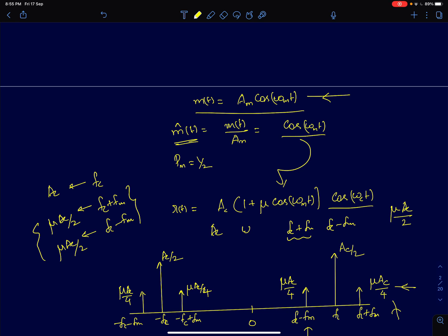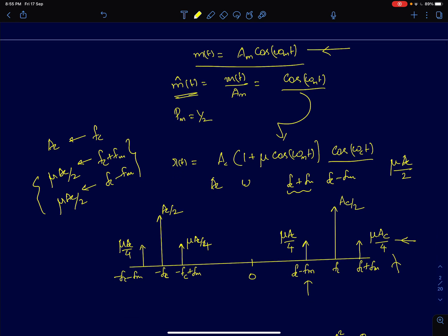Now, to plot its Fourier transform, you just have to plot the Fourier transform of sinusoids. In this case, when you transmit cos omega m and cos omega ct, both the carrier and the message signal are in phase, so you will get purely cosine signals. So you can plot for Fc, you can see the signal amplitude, half the amplitude is on the positive and half on the negative side. So you have to construct a cosine cos omega ct using two complex exponentials with half the amplitude of the sine wave. So that's where you see two impulses with the same weights but half the amplitude.